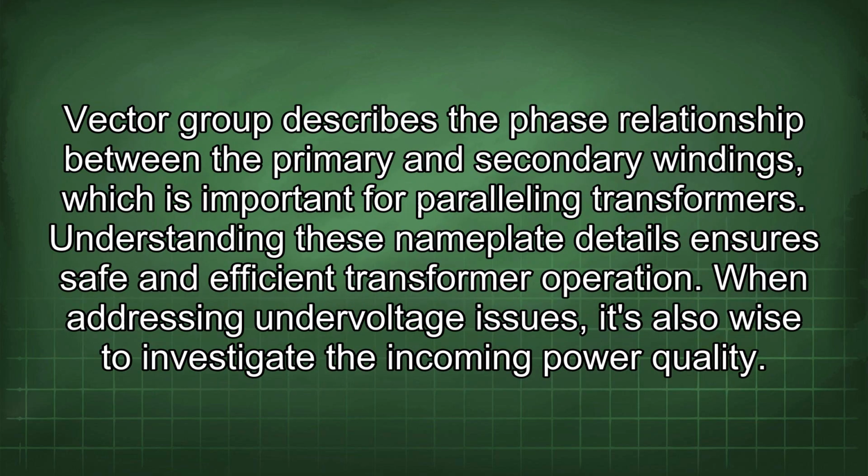Vector group describes the phase relationship between the primary and secondary windings, which is important for paralleling transformers. Understanding these nameplate details ensures safe and efficient transformer operation.